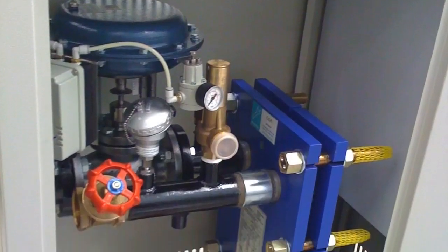Allow me to clarify, it is significantly simpler to heat cold water using extremely hot steam that is readily accessible, as opposed to heating water that is already warm using slightly warmer water. If we need to heat water for a domestic heating system to 70 degrees C, and we have water available at 75 degrees C, everyone understands that it takes a long time. Why? Because the two temperatures are very close. If instead we have steam at 130 degrees, heating water to 70 degrees is easy.